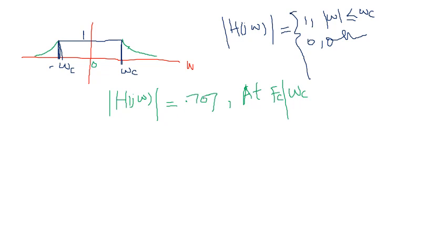You are all electrical engineering students, so you understand practical filters are built from resistor, capacitor, and inductor. If we talk about the first order filter, the order means the number of capacitive and inductive devices included. So in the case of a first order filter, you can make it either from resistor and capacitor, or from resistor and inductor.